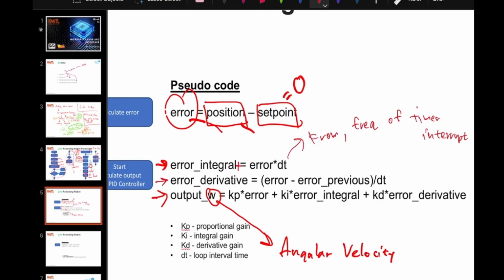So if you set the period of the timer interrupt to around maybe 0.01 for 10 milliseconds, you have to set dt to 0.01. And you remember you have already learned from programming, everything should be float, right? Because it is a decimal value.